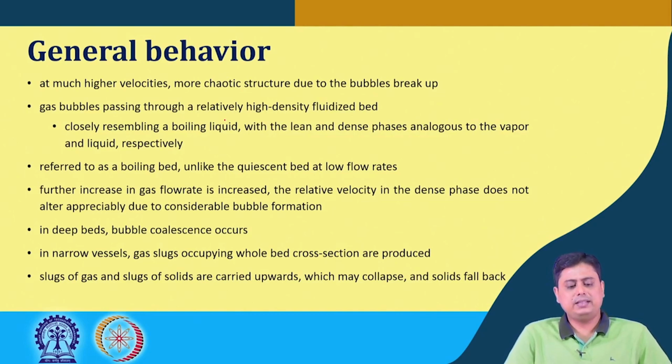And with further increase in gas flow rate, what will happen? The relative velocity of the dense phase does not appreciably change, because the maximum portion of this gas is now contributing towards the bubble formation and its breaking and participating in such phenomena.